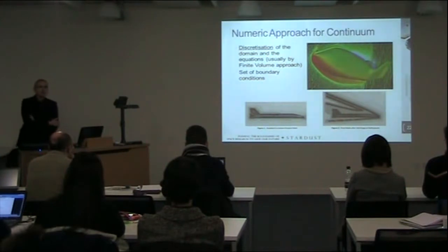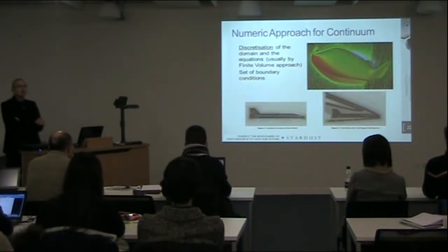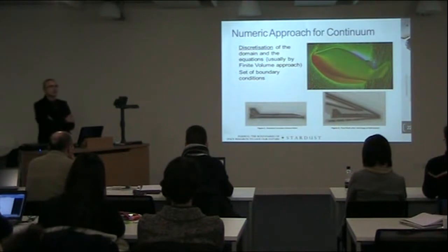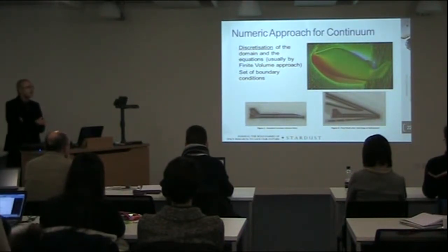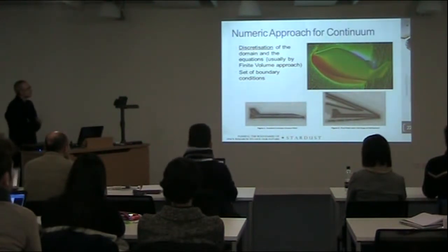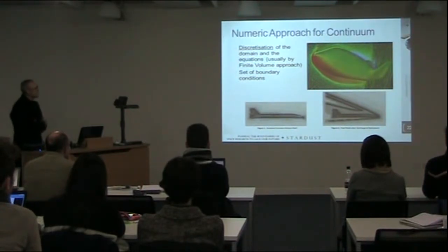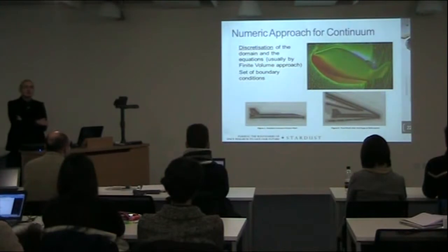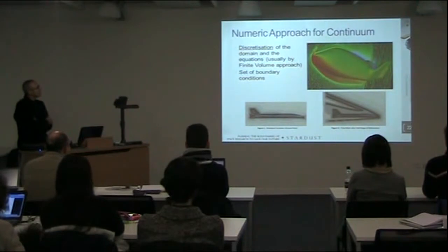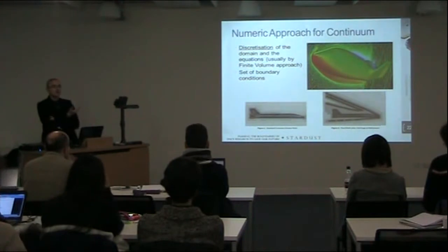To obtain the solutions of the problem, what you have to do is use the normal, almost normal techniques used for the computational fluid dynamics approach. So the discretization of the domain and of the equations, and this is mainly done now using the finite volume approach. And then you have to set boundary conditions, for example, on the wall, and boundary conditions at the inlet, depending on how you design your domain.